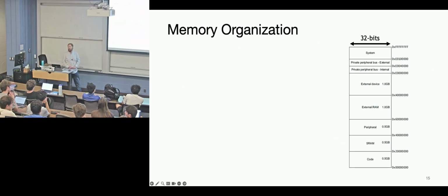Yeah. It's because they want the other vendors to expand on the other unallocated memory, so in the future they can have some other peripheral. Yeah. So part of this comes down to remembering what ARM's business model is. They're not trying to give you the one microcontroller. They're setting up an architecture that allows vendors the flexibility to choose how much SRAM, how much peripheral space they're going to need. So if you're a vendor that's making a very small version of a microcontroller, say it's only got 4 pins or something, these things do exist, you're not going to really need that much space for peripherals because you don't have that many registers in there, right?